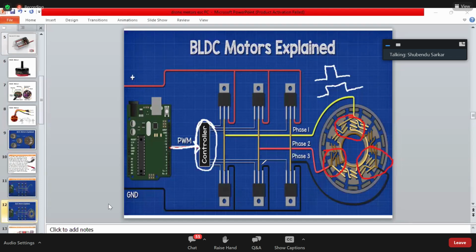It is going to change the speed of the rotation. Okay, that is the point we have to understand. With the help of the PWM signal, we are going to tell the ESC that now you have to increase the speed. When we increase the width of the pulse, the speed of the motor is going to increase, because the ESC understands the pulse is increased.